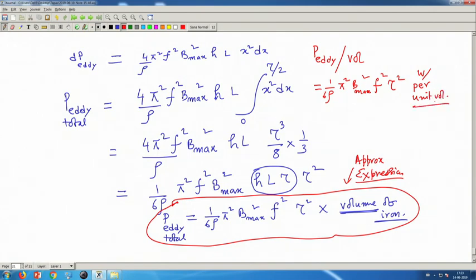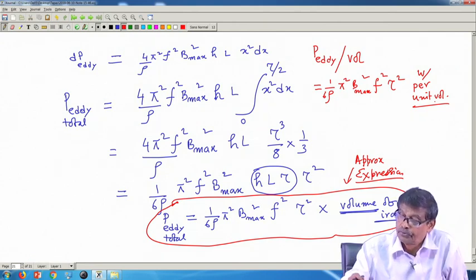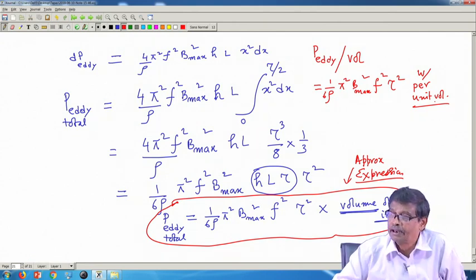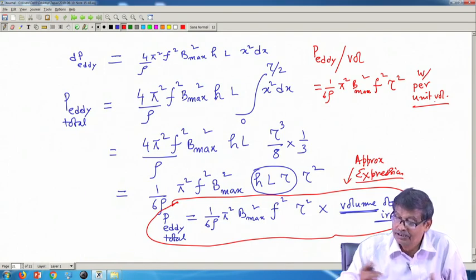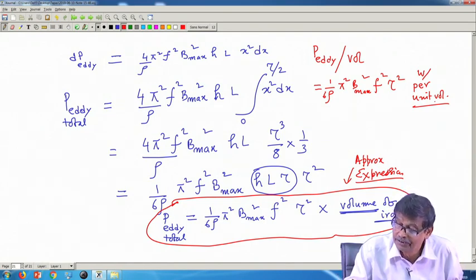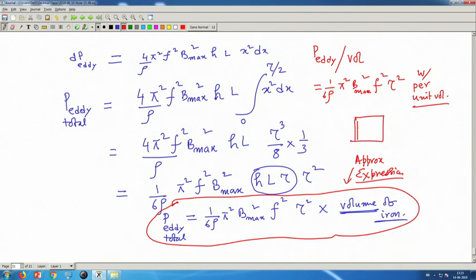And we say that then eddy current loss will be proportional to the square of the thickness of the plate. See, all these things, the argument was, if you use a solid block of iron, eddy current loss is bound to be more, so many eddy paths.